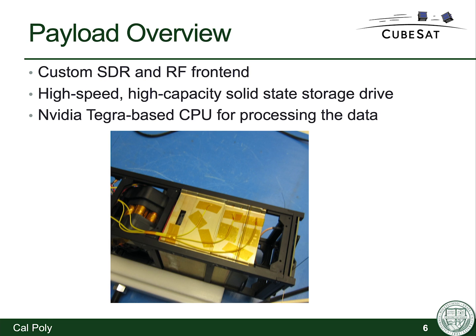As I mentioned before, SRI provided the payload. The payload consists of a few different components. There's a custom software-defined radio and RF front end to observe the digital TV signals while we're taking our observations. This was in turn tied to high-speed, high-capacity solid-state storage. Each observation generated gigabytes worth of data, so a very large data set at a very high rate.